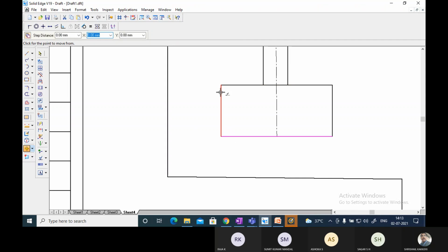This portion of the machine, this one is worn out. Now this height is also very, very important for the programmer. This axis movement, how much it has to move, that is also important. So these are all the inner things. The sensor will be there, it will be measuring, it will be compensating the tool wear out.